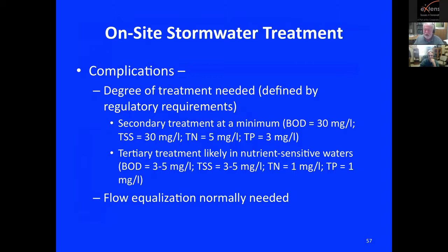some chemicals out of the water. We can use settling treatments for phosphorus. Nitrogen's a little bit tougher. We probably have to go through some anoxic conditions and then go into an oxygenation section.